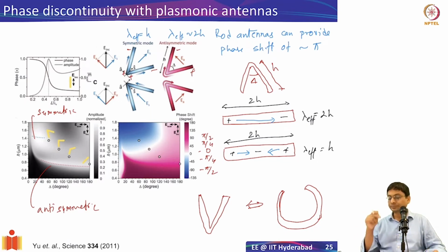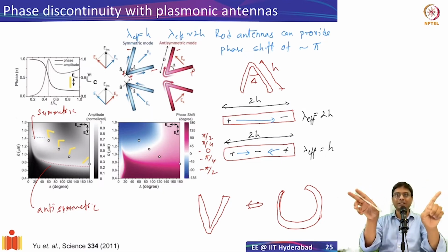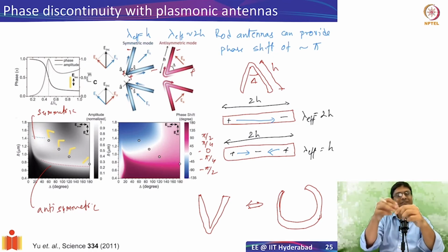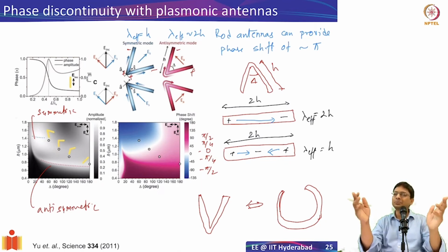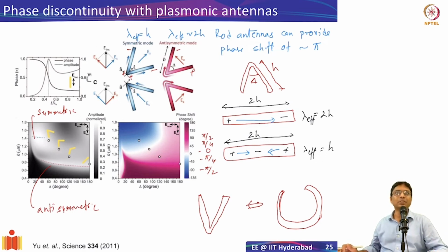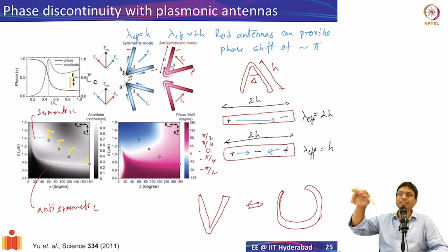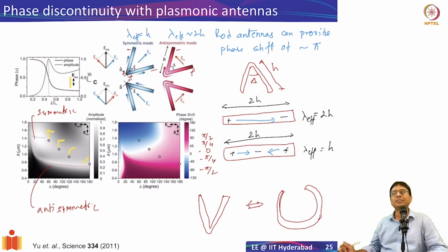The main thing is the gap was important. It's not like a split ring in the true sense, because the gap is quite wide. If you have a very small gap, then you have a capacitance associated with it, and then it becomes a double negative structure. But in this case, it's not going to be double negative, because the capacitance is not going to be that large. So most likely it's not going to be double negative, but it can potentially exhibit negative mu. We'll have to look at exactly how strong that is. It depends on the displacement current as well. Because it's very far apart, maybe it will not be. We'll have to see. Okay. But definitely, once you have a circulating current, we should see some magnetic response. All right. That was a very nice question.